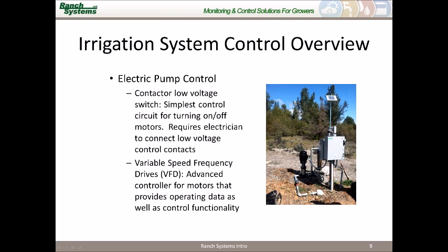However, it provides the entire control mechanism, so you can change the set point, or the PSI, that you would like to hold the system at, and it adjusts the frequency of the pumps or motors to match that PSI. As valves close and other valves open, it adjusts the frequency and actually turns the pump on and off in proportion to demand.